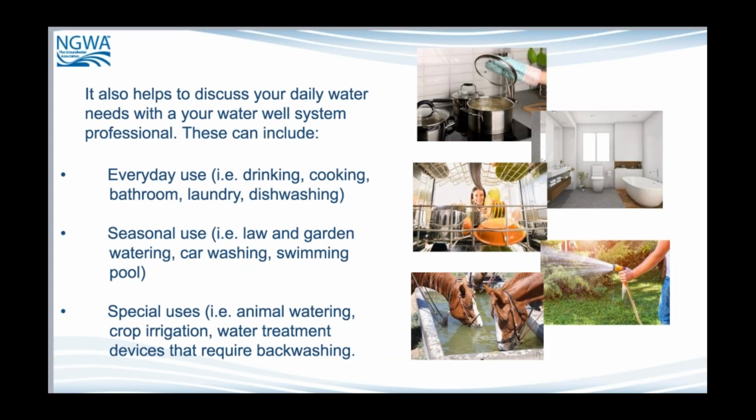I've seen customers before that have gone ahead and they put in what I call a people wash. It was a 30 gallon a minute shower, which is a huge amount of water. When you consider that your standard faucet at home is going to flow something like 1.8 to 2 gallons a minute, you're talking like 15 of those run full blast. The problem that we had there was we could only get him like 23 gallons per minute was all we could get. And he asked us what he was going to do about a shower. We had to tell him that he had to take some of the shower heads out of the design. He was not going to have enough water to supply the shower the way that he wanted it.